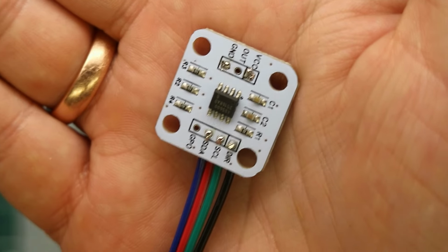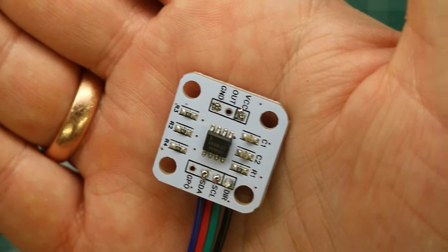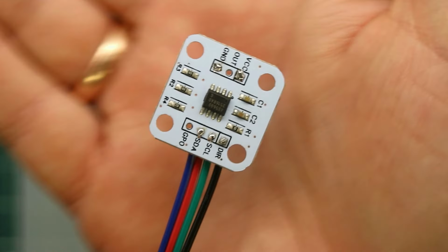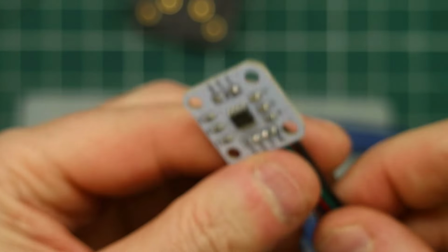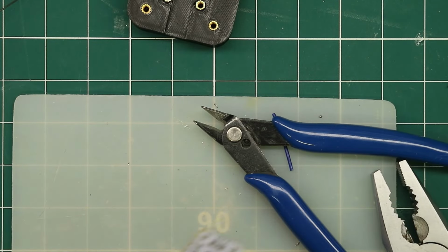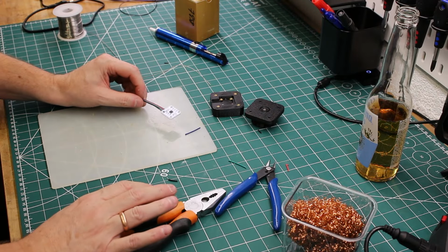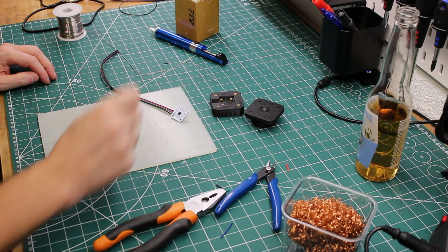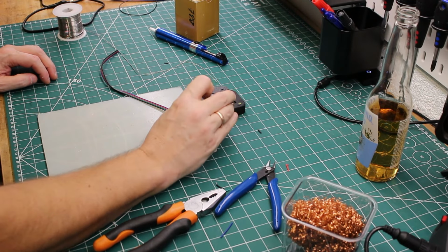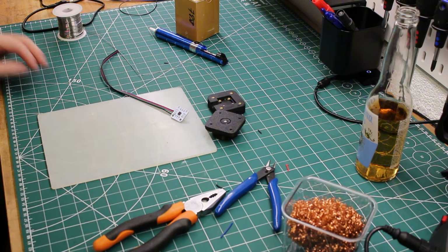The out is an analog signal, so if you want to just attach it to an ADC, you can do that, or you can talk I2C to it to get the readings, which is what we're going to do. Next up, we'll attach it inside the box, but I think we have to wait for the glue on the magnet to set before we can continue that. So I'll meet you back here in about half an hour.